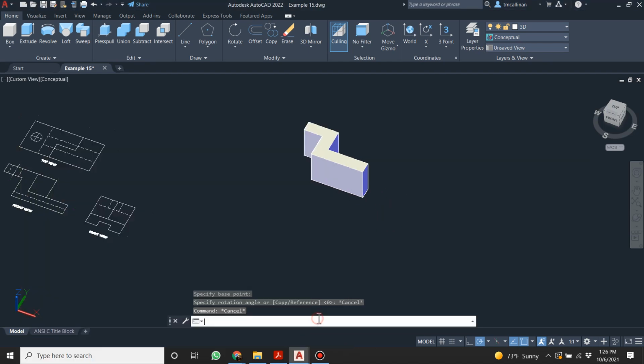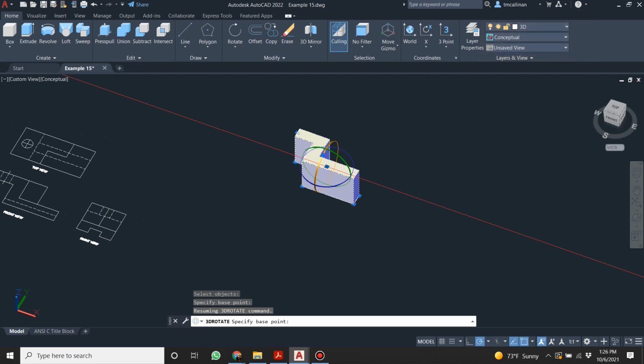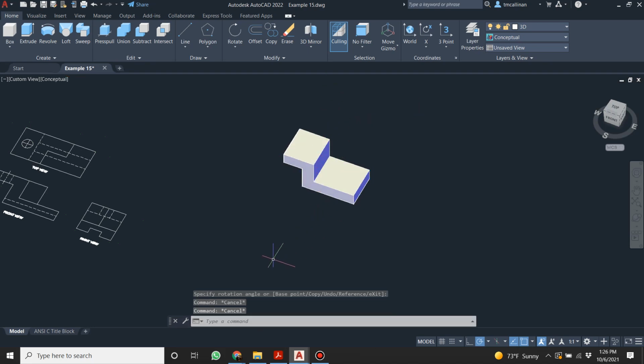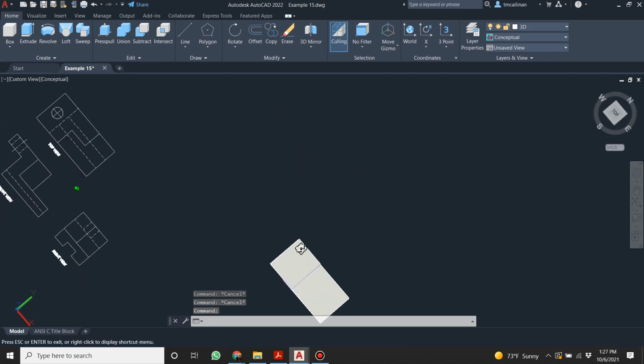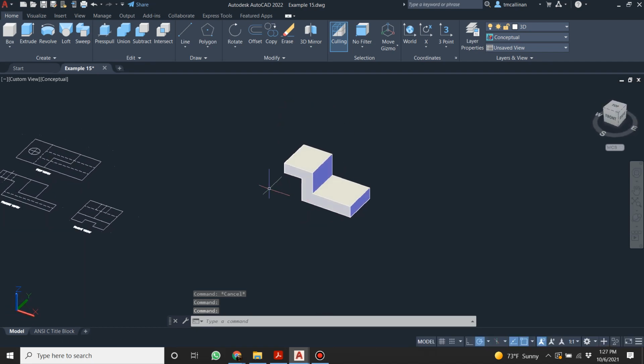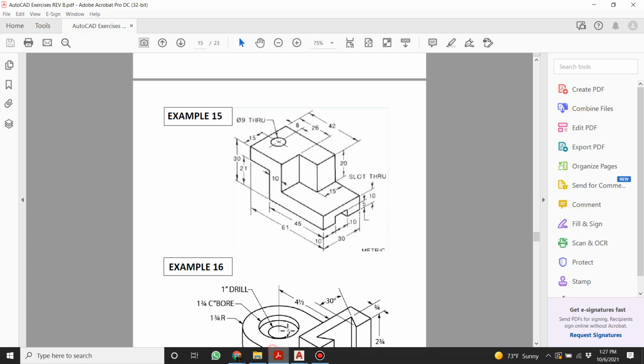Now if I type in 3D rotate, and I go here and I press enter, oh look at this. I'm going to grab the red, and I'm going to spin this until it locks in there. And now that's a bit better. I can work with that a little bit. I know your heads are probably melted. Okay. We're going to draw this little rectangle and extrude it up.